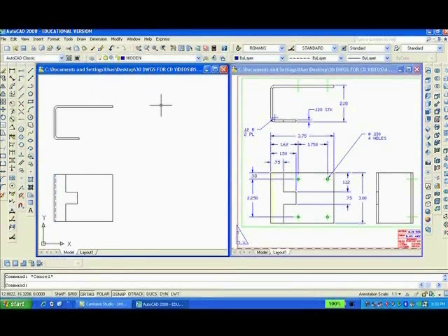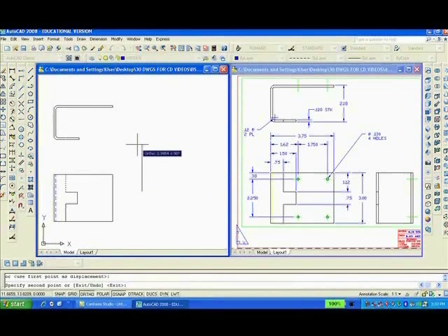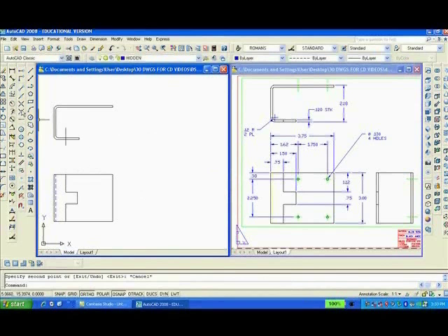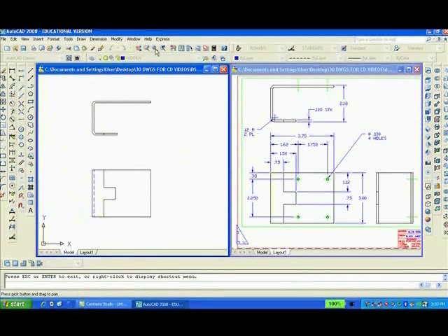Next thing we want to do is draw the right side view. Well, I'm not sure that we really need it because it's quite self-explanatory without it, and there's no dimensions on it. So we'll ignore the right side view, and we'll copy this line and drag it up here like that. Enter or escape, and then we're going to trim from both of these lines. Then we want to pan over and enlarge this view.